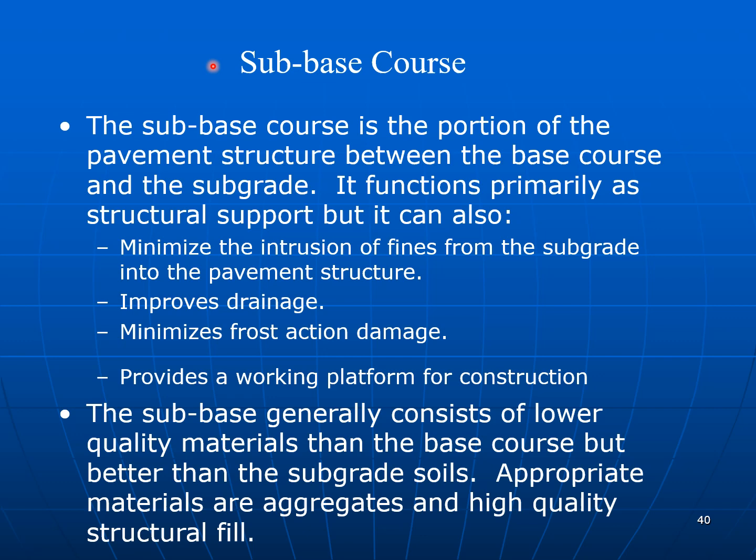Subbase course. The subbase course is the portion of the pavement structure between the base course and the subgrade. It functions primarily as structural support, but it can also minimize the intrusion of fines from the subgrade into the pavement structure, improve drainage, minimize cross-section damage, and provide a working platform for construction.